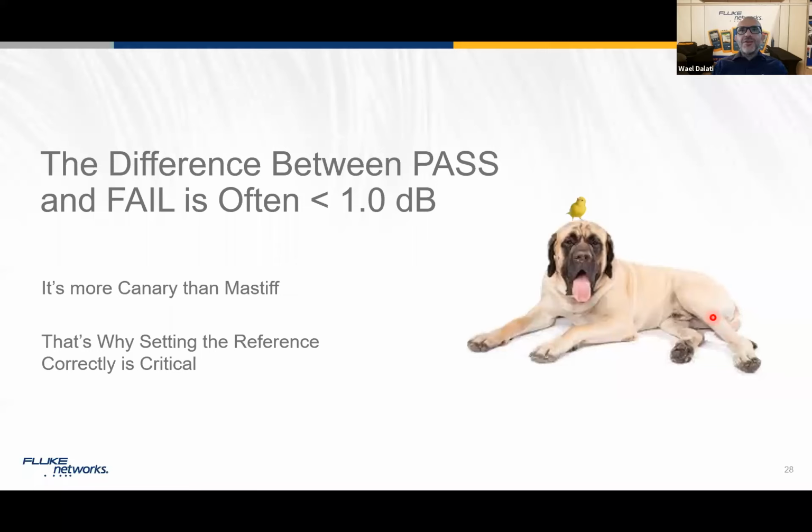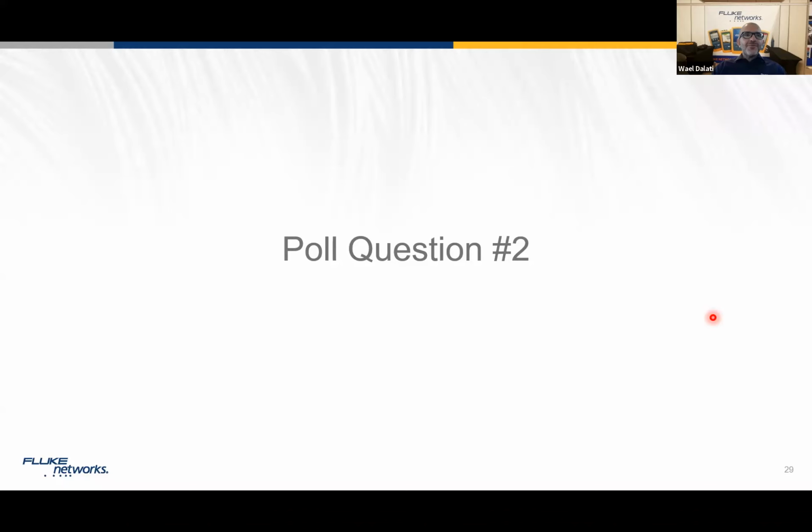That's the purpose of my next poll question. Jens, if you don't mind, please help me with the next poll question. The next poll question is: how often do you set a reference in fiber optic measurement? We've seen people in the field carrying loss measurement light source and power meters, or optical loss test sets, and we ask them how often they do that. We get different responses, and I wanted to have that conversation with you, ladies and gentlemen, to understand the importance of the reference, because as we tighten up our limits, doing things right becomes even more important than ever before.